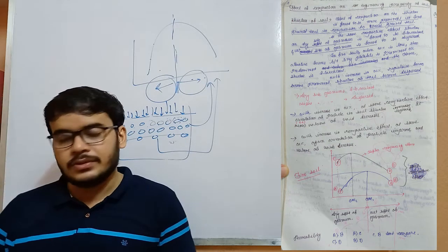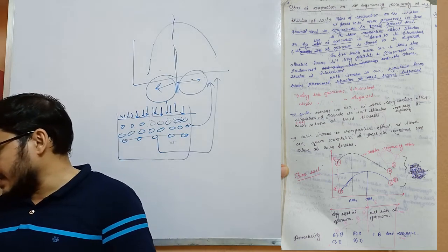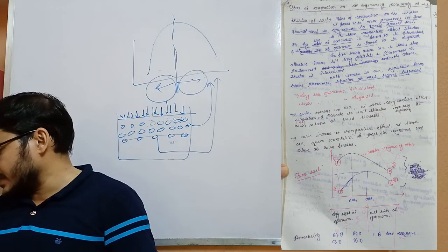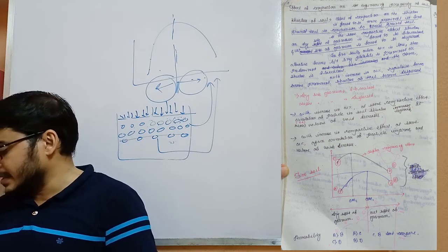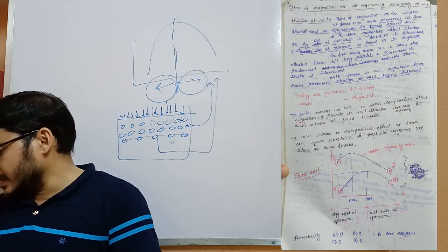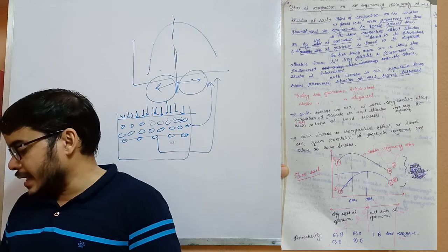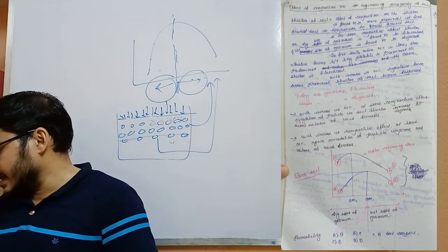Wet side. With increase in the water content at some compacting effort, orientation of the particles in the soil structure improves, and it means volume of voids decreases. With increase in the compacting effort at the same water content, again orientation of the particles improves and volume of the voids will decrease.